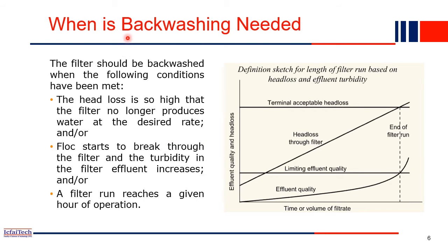Now, when is backwashing really needed? That's what we have to monitor: the head loss of water, how much head loss has taken place. This is the graph you see, time versus head loss. Initially the head loss will be very small, but as time goes, it increases gradually, and when you reach the acceptable head loss limit, you discontinue and close the operation and perform the backwashing.